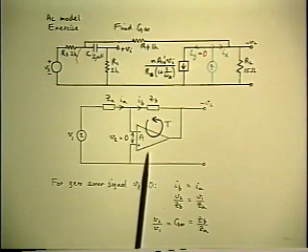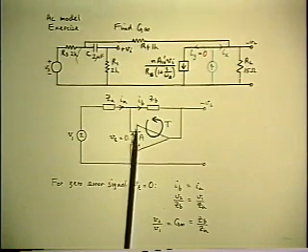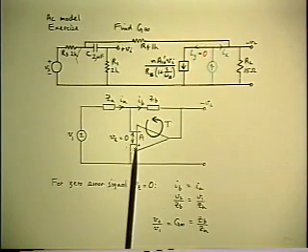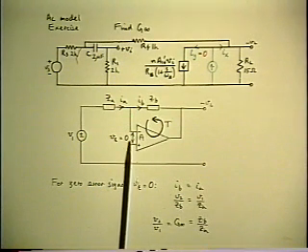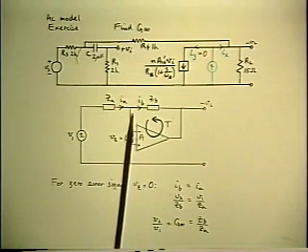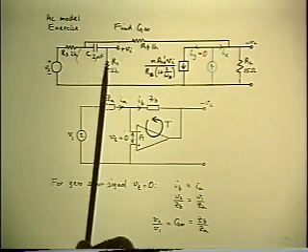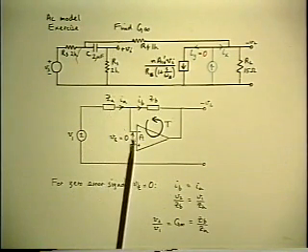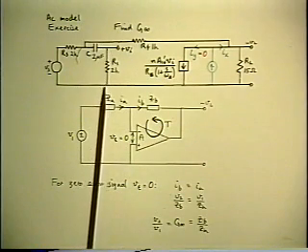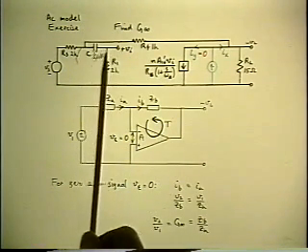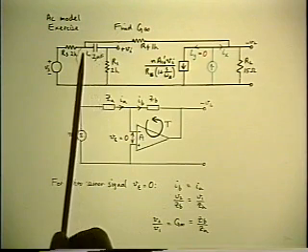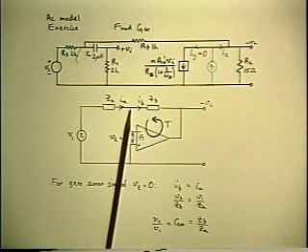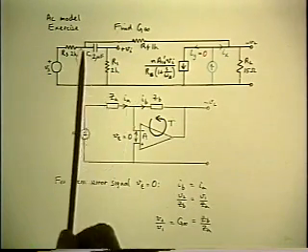And I already emphasized when we talked about this previously that you make no assumption to do with the input impedance. It doesn't matter whether it's 1 megohm or 1 ohm. The null condition still means that if you have 0 voltage across it, you get 0 current into it. And it's the same thing here. You've got 0 voltage across a 2K resistor, but you still get 0 current in the resistor, therefore 0 current in the capacitor as well. So the feedback summing point is equivalent to the same summing point here, and it is a virtual ground.